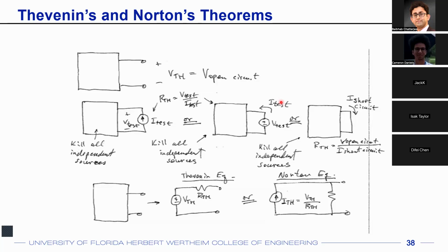What is most important to remember here is that while you are trying to calculate the Thevenin equivalent resistance or the Thevenin equivalent voltage, you want to make all the independent voltage sources inside the black box, or anywhere else connected on the black box or in a circuit diagram, 0, and you want to make all the independent current sources an open circuit.